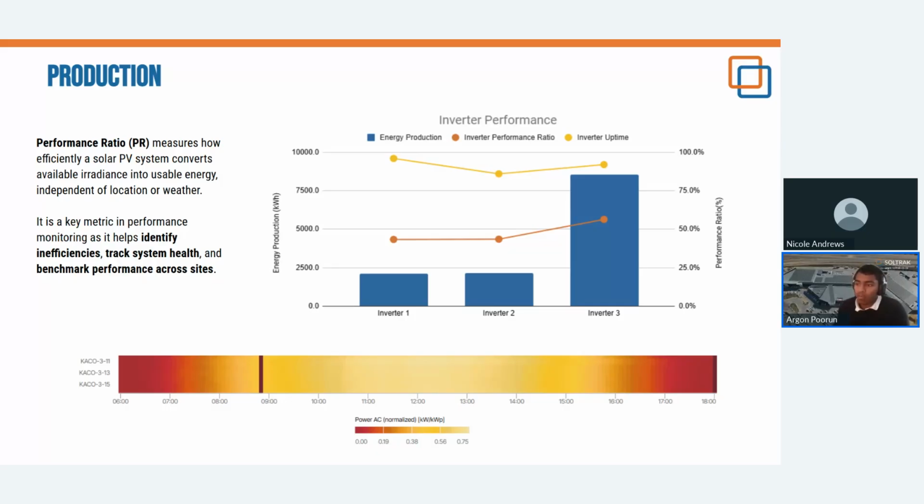You could have scenarios where the meter data is unavailable or unreliable, and hence you need to default to a secondary data source, which could, for example, be the inverters. On the same side, you could have inverters that lose comms, and you would at least have the meter data as your primary data source.